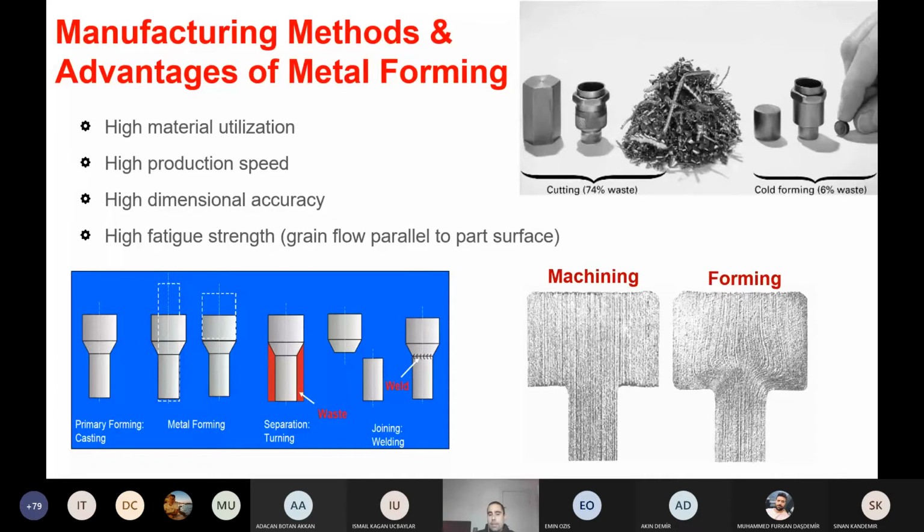And if we consider casting, it is much worse because we have porosity, some small holes in the part, which is a little bit inevitable. It can be minimized. There are some advanced casting equipments where we can lower these flaws inside the material, but still compared to forming, the performance of a cast part will be more or less, or in most cases, less than the formed part.